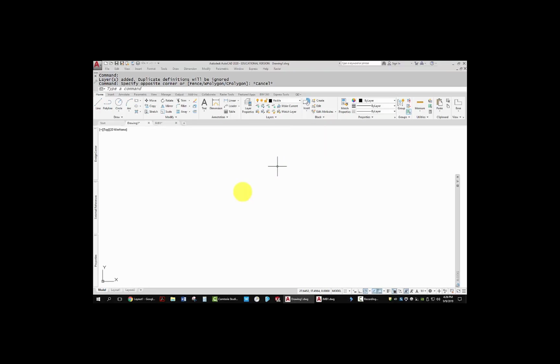I'm just going to pick a starting point of 0, 0, using a line command or the P-line command. L for line. Starting point 0, 0. I can type in as an absolute coordinate. I'm going to go down until I have polar tracking. Go 4 inches. I'll zoom in using my mouse. 2.5 is the height of this. Now I'm going to go over and acquire the endpoint of the first line by hovering over it. When I get the two tracking lines, I'm going to left click, type C for close, and it's going to go back to the beginning.